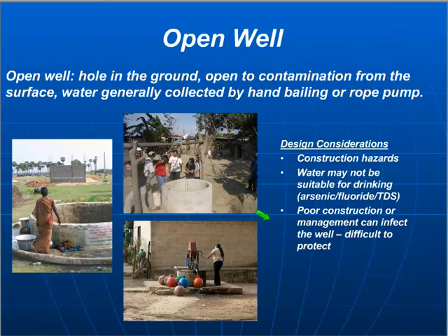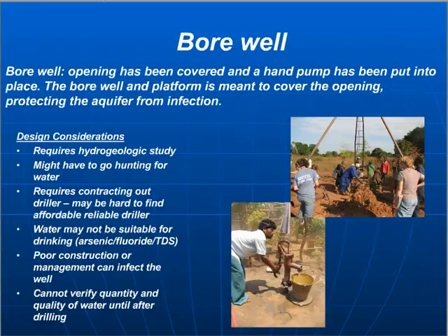And any excavation that's beyond 3 feet, there's this potential for collapse of the soils that, if it's above the height of a person doing the excavation, that's obviously very dangerous and something that we take very seriously, and you'd have to have a plan for that. And again, the issues with the water quality is always a concern with open wells like this. And so typically they're in the center of town, and so that makes the problem even worse, that it's hard to just manage the land around that area and limit activities that might cause pollution.